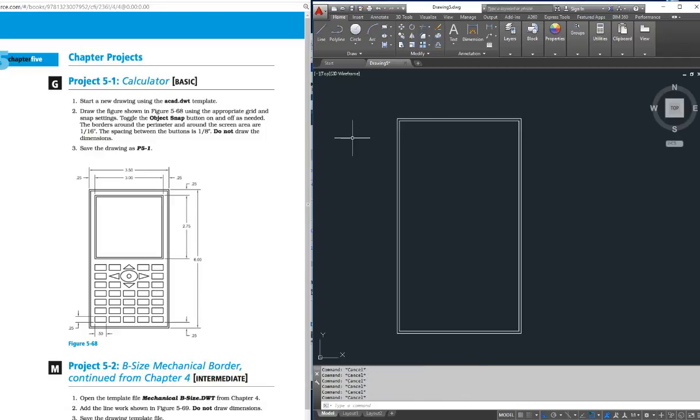I'm going to offset. Let's do the X line thing. X line. And I'm going to say offset, and I'm going to say 0.25. Enter. I'm going to pick the outside. Pick the inside. And that'll give me my offset for my 0.25 that it specifies right here. Okay, so now it says it's 3 inches over there.